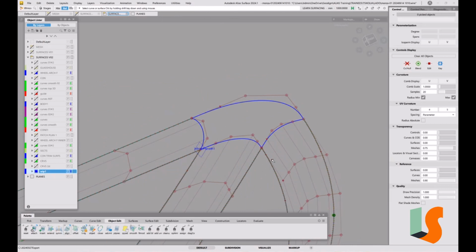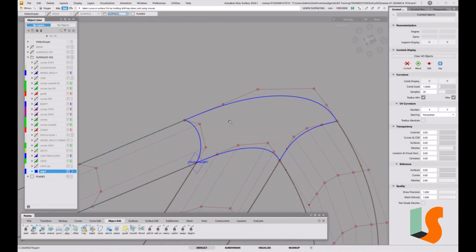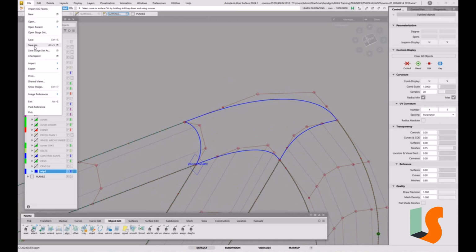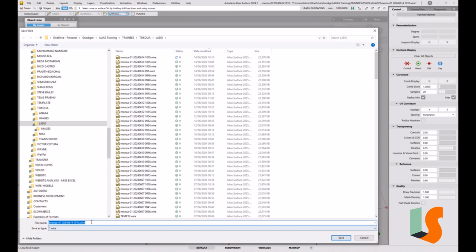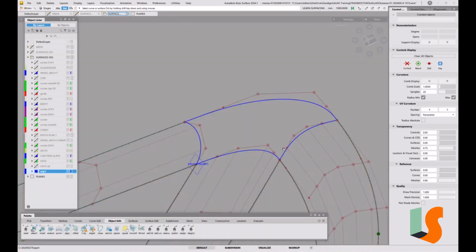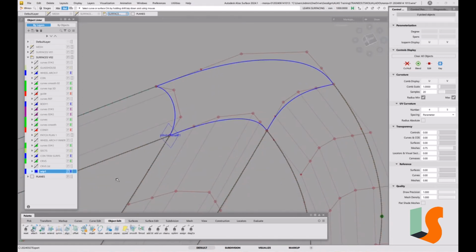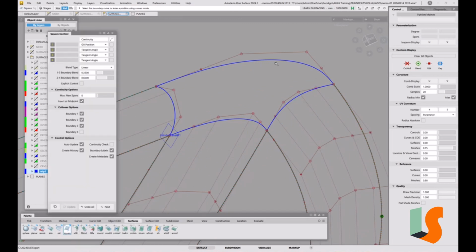And then I need to get from here to here. So you've got G2 on this one and G1 on this one. So this is slightly more complicated in a sense than usual, where I've shown you G2 to G2, and that's quite straightforward, because you know how these CVs are going to join up. So let's go. So this is where we need to be careful when we put in our corner. So we've got square, we've got G1 position on there. This end is G2, because that direction is G2. So if I go around picking that way, so this is G0, G2.